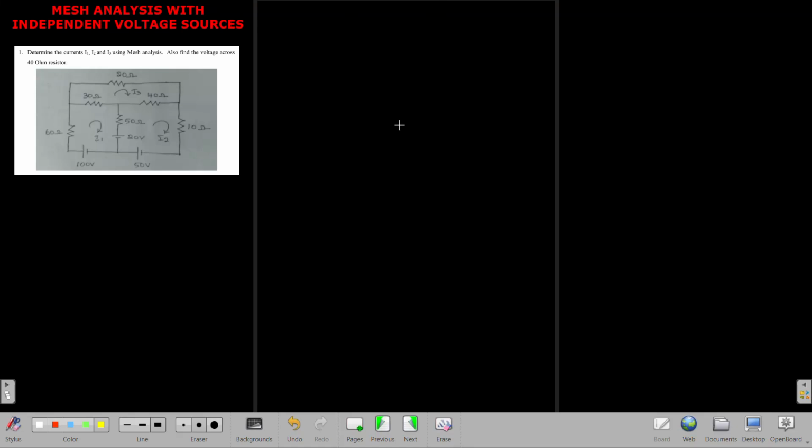Welcome, you all. In this video, we will learn how to solve the circuit problem using mesh current analysis. So one thing you first need to see when you are trying to solve the circuit problem using mesh current: see to it that your circuit has voltage sources or current sources. If the problem is given with voltage sources, then it is pretty much straightforward.